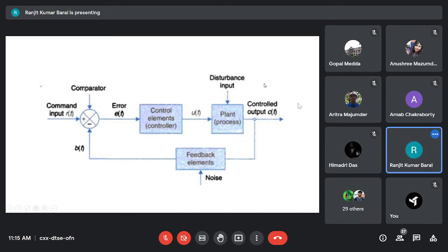Possible, provided you perform a few operations with that transducer. First of all, you have to characterize your transducer. You have to find out its characteristics, the voltage generated versus temperature characteristics. If it is a nonlinear characteristic, then you have to add some circuit to linearize it, because nonlinear measurement with a nonlinear system is not so easy. So you have to linearize the characteristics. Then if it contains measurement noise, you have to filter out the noise.